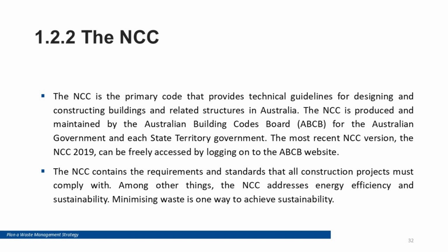The National Construction Code is a key reference for building work in Australia. While the NCC is not a waste manual, it influences material choices, construction practices, and performance requirements that affect waste outcomes. It is supported by referenced Australian standards and may include state or territory variations. When planning waste minimisation, check how code compliance affects what materials can be used, how they must be installed, and what documentation is required.